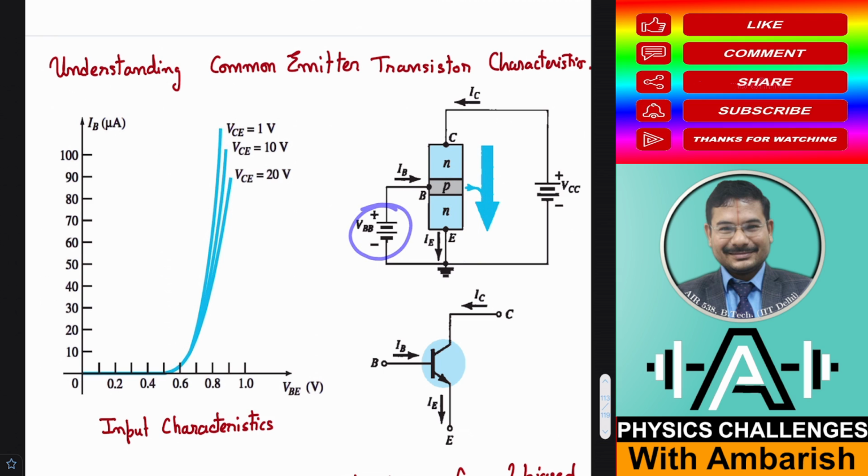In semiconductors, it's often convenient to think of a battery as not just emitting positive charge. Think that the battery is emitting electrons from its negative terminal, and holes from its positive terminal. Simultaneously it is emitting both. You can imagine the battery to be like that; often that visualization is helpful. So what's happening from the negative terminal of the battery? Electrons are being ejected into the emitter.